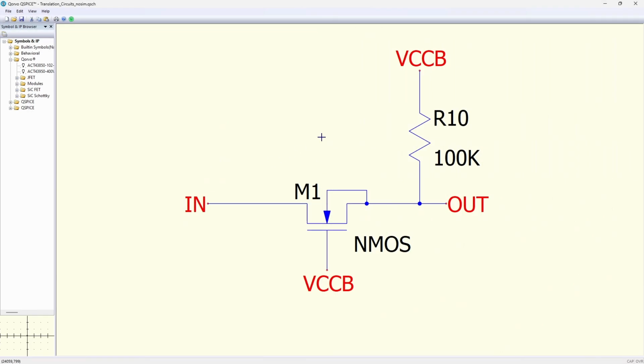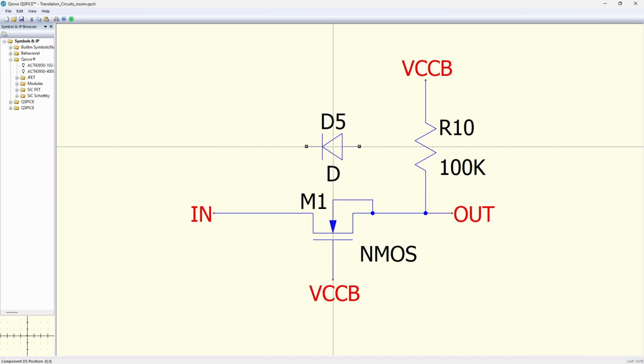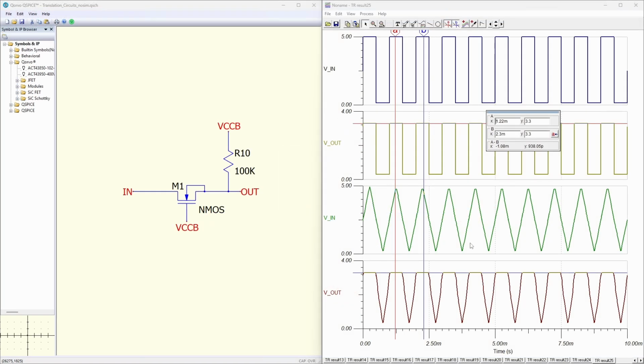This next circuit changes out the BJT for a MOSFET, and it works basically the same way. One thing to watch out for with FETs is that they have an intrinsic diode that's going to connect the source to the drain in this way. So you definitely want to make sure to connect it the right way around, otherwise you'd be connecting your input directly to your output through a diode. And in my simulation you can see that I'm getting exactly 3.3 volts at the output.